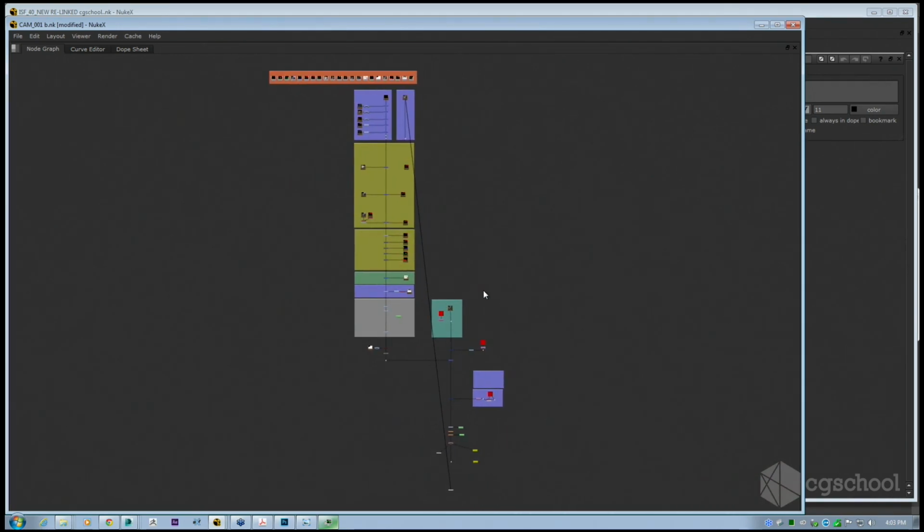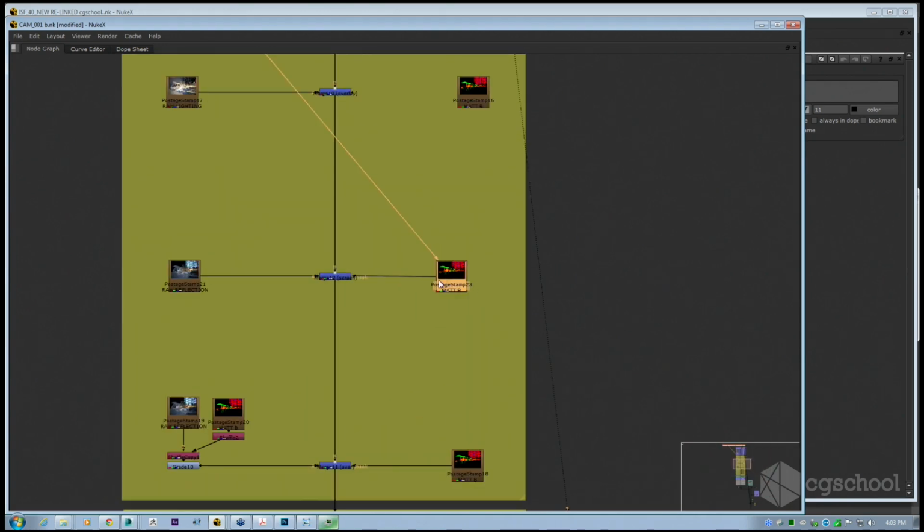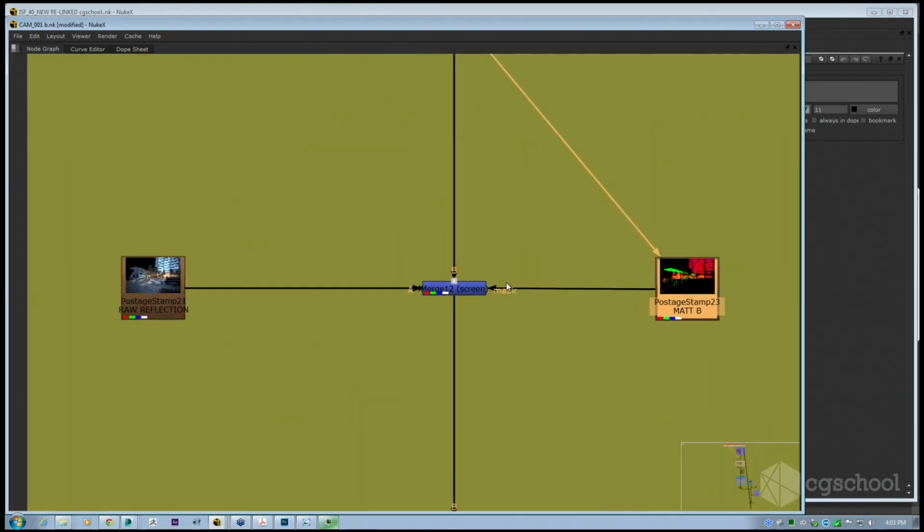All the models are worked on by several different artists throughout the day. The lighting is slightly changed, and then essentially all we have to do is select our folder within Backburner, press restart, and it's going to take all of that new data, render it again, update these files, and then every adjustment we make here is automatically updated.